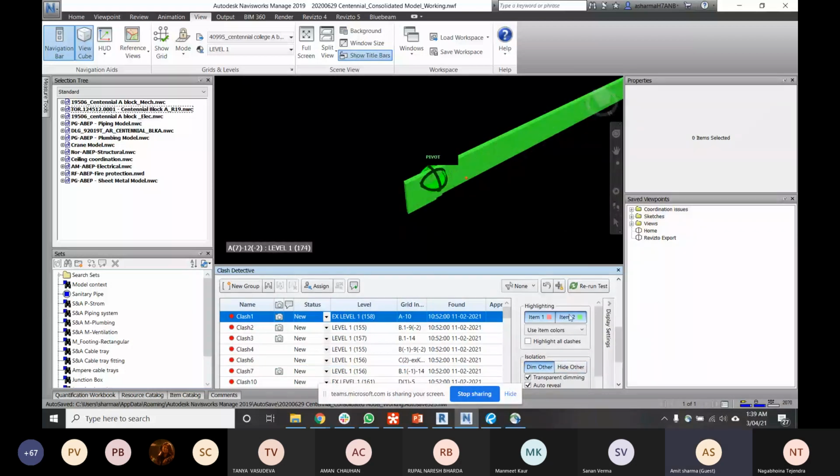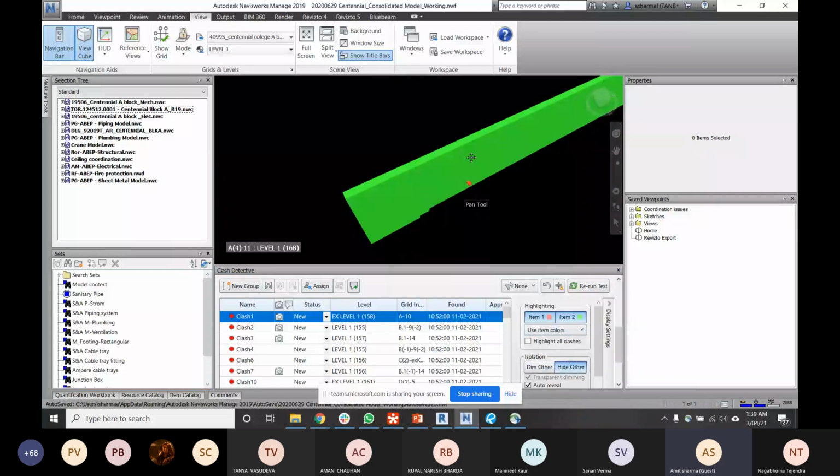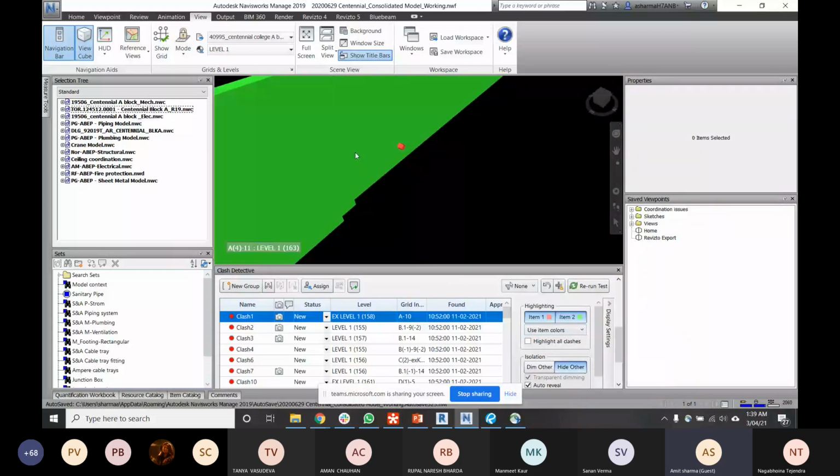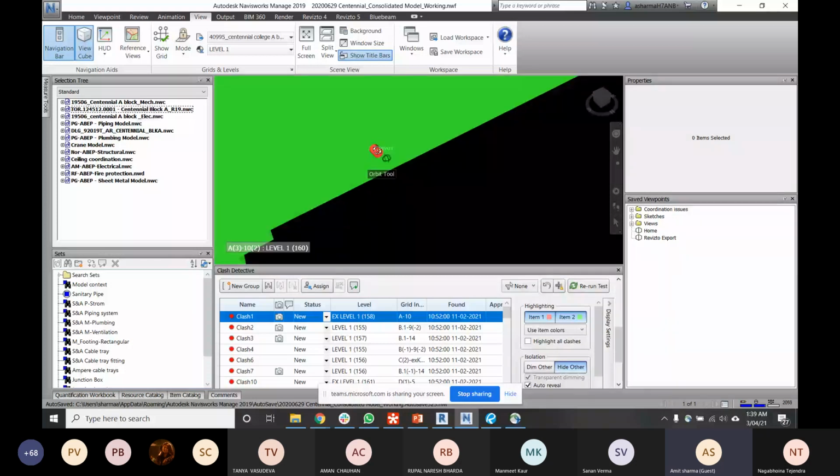So imagine a position like this. Here I can see, if I do a clash section, that one of my pipes is going through the structure wall. Okay. What I do is I do a clash section, I see an issue, and I export this model in a tool called Revizto.